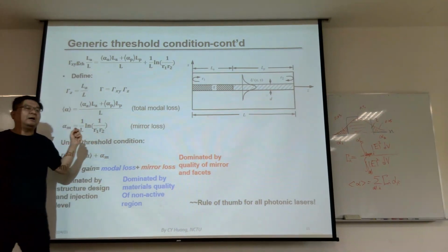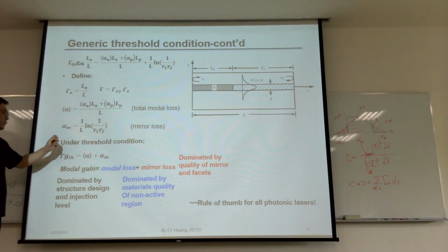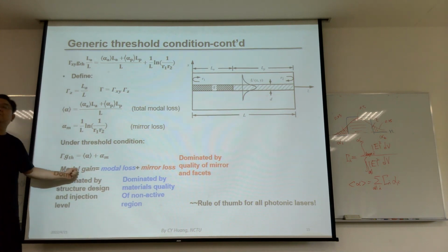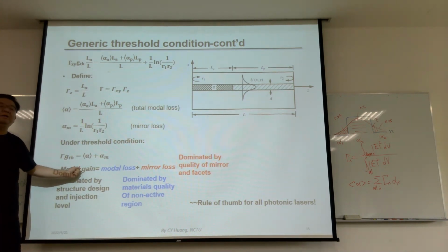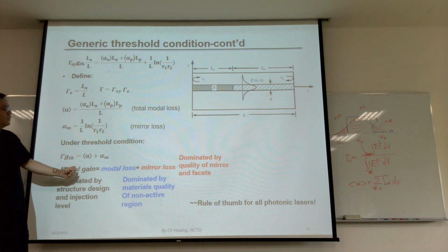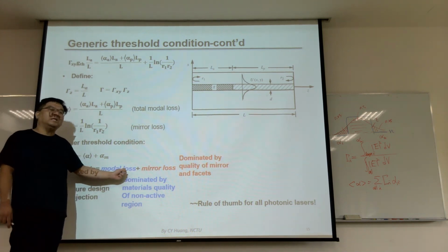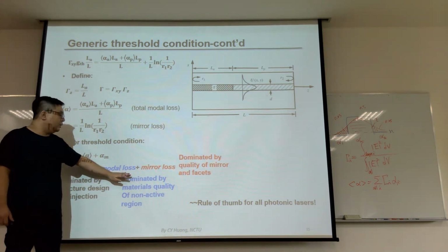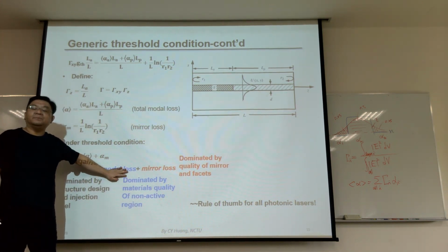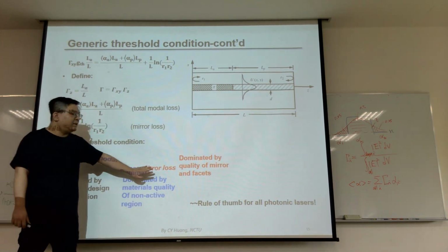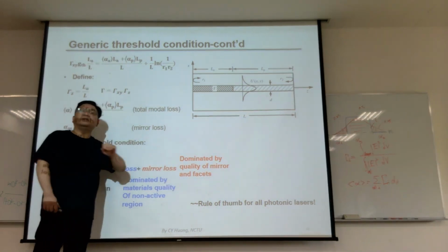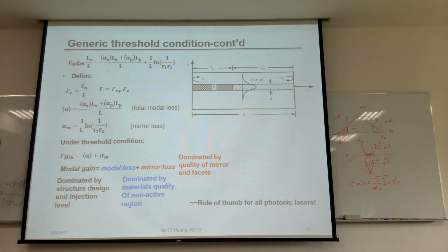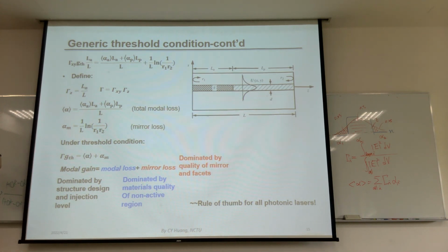How does it lase? It lases when the optical gain or modal gain provided by your active region equals the loss from absorption by its material and the energy leaving its cavity. While these two terms balance, the semiconductor will lase.